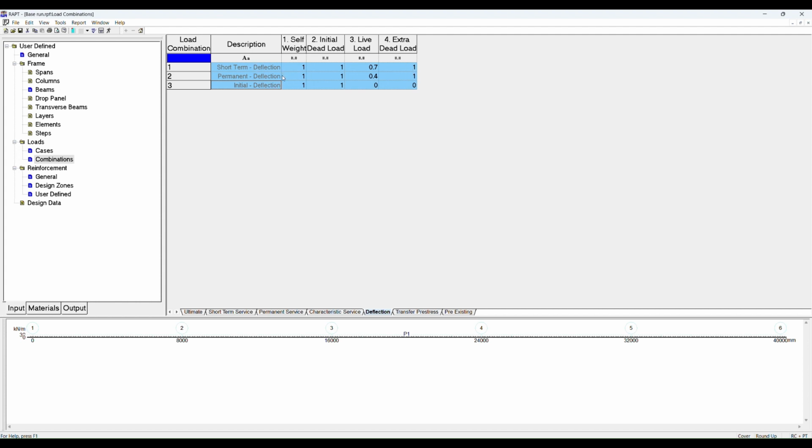That gives you your total long-term deflection, including the elastic deflection at the end of 30 years to account for this 0.7. Incremental will then take that load case that I just explained and subtract your initial deflection. If you go to the help menu by clicking F1 right here and going to theory, it'll give you explanation in great detail if you need more information.